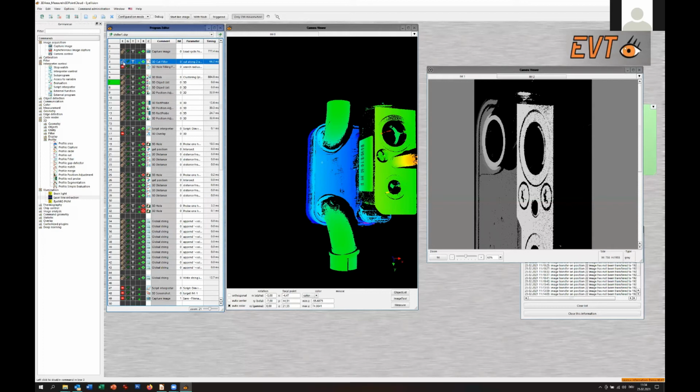With the right mouse button, next you have execution control. This is also very helpful, especially if you do programming, to see what program is done when. You can control if the tool is executed always; then you see these two gears, these brown things. Or if the tool is never executed, you see the don't-drive-through sign, the blocked sign.